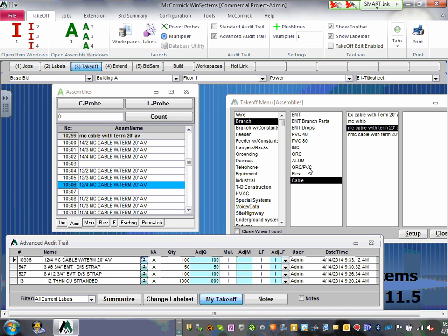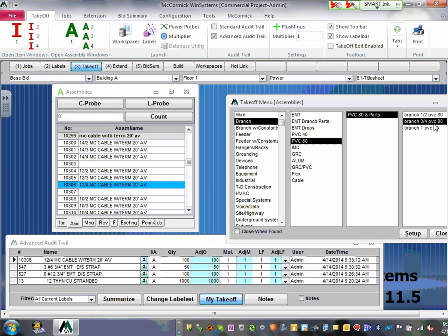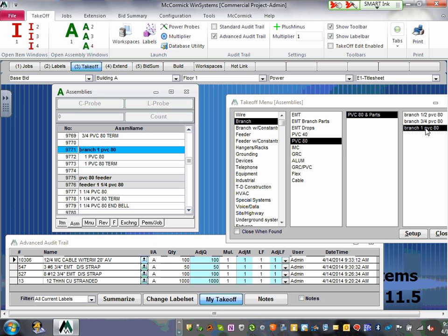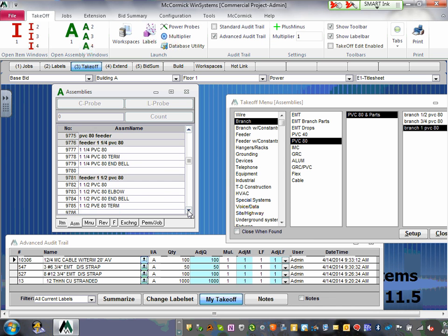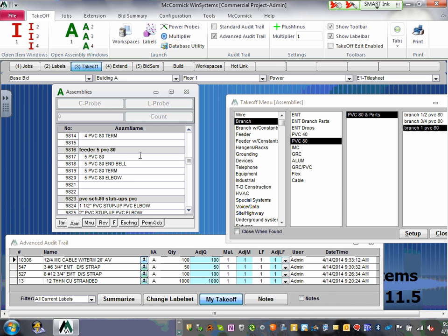Now, if you're going underground, Adam, and you need a conduit to bring the service, PVC Schedule 80, click on PVC Schedule 80, gentlemen. It only goes up to 1 inch, though. I'll show you where to find the other ones. 1 1/4. If you look underneath them, 1.5. Can you guys see it goes right here? If you click, can you guys see it clicks 1.5. 2 PVC Schedule 80 2-inch, 2.5. Up to 3, 4 inches PVC, 5 inches PVC. Everybody can see that? 5-inch PVC.